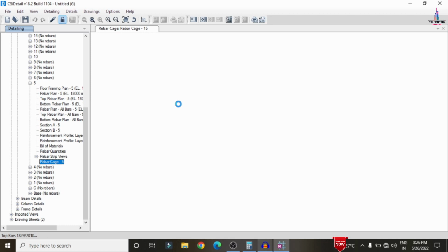In the same process you can click on the beam detailing, concrete beam detailing, elevation section, select any one of the floors. So it will consist of the reinforcement values here, which consist of all the details. But here as per the considerations of the vertical irregularity, it is showing no bars for the respective beam. But if you design with the perfect design consideration, it will show you the reinforcement values. In the same process I am selecting the column designing section. So column designing also is not showing any kind of reinforcement value for the column section. Okay, so this is the complete process of G+15 structural model vertical irregularity building structure design by using ETABS software.